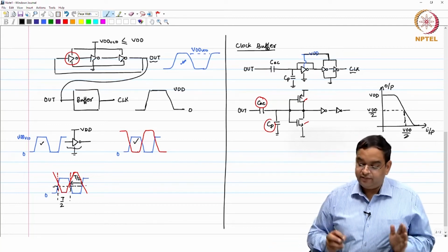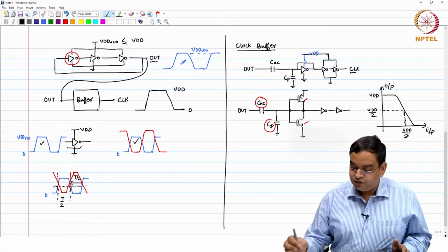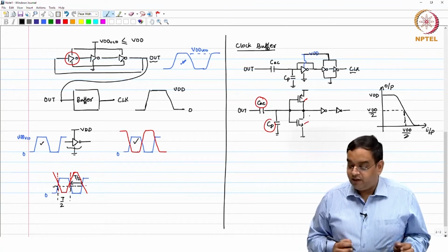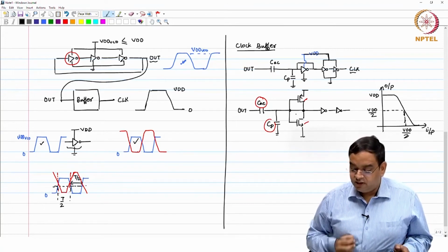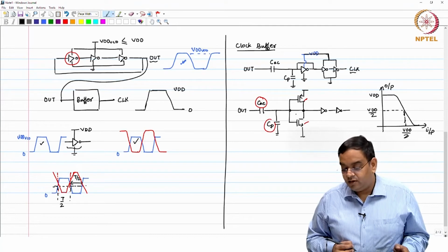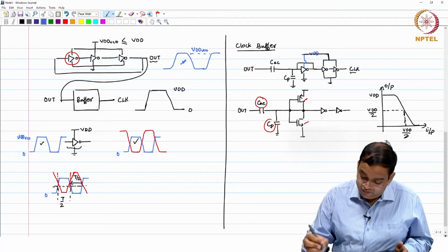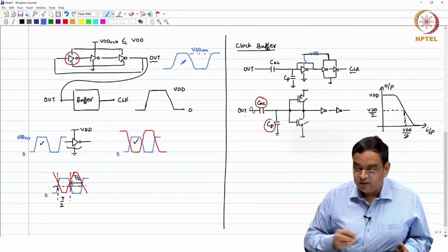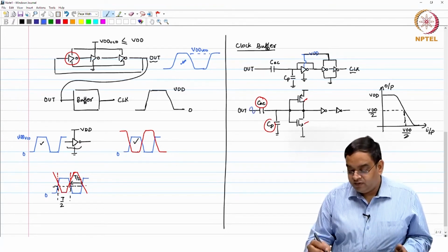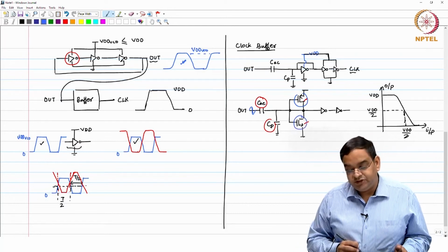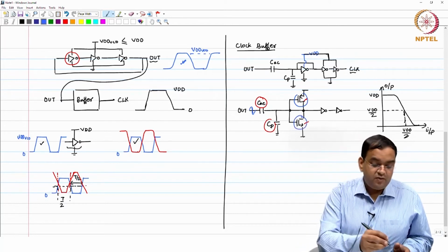Okay. So, you have that, choose the PMOS and NMOS sizes accordingly, right. So, this is a nominal operating point, you get this capacitor. So, when you have any frequency coming here, what that signal is going to see is a loading because of the PMOS and NMOS current sources here and CP both.